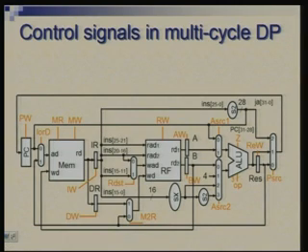So, these are three inputs to this multiplexer: after the register, before the register, and this jump address. Recall that we will write output of ALU directly into PC when we are doing PC plus 4. We do not bring register into picture, but the target address for a branch we are temporarily keeping into this, we are not directly transferring to PC, and therefore, when we transfer to PC we will take from output of the register. So, therefore, both paths have been provided.